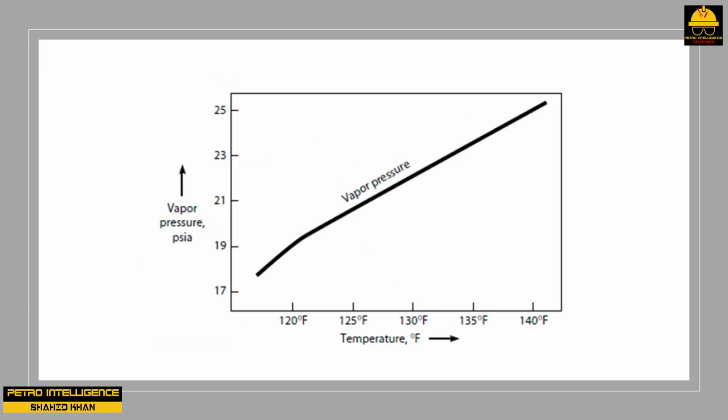As can be seen in the picture, subcooling this particular liquid by 5 degrees Fahrenheit reduces its vapor pressure by about 2 psi. As the specific gravity of the liquid is 0.58, this is equivalent to an increase in the NPSH by 8 feet. Once again, our objective is to increase the flow from 250 to 300 GPM.